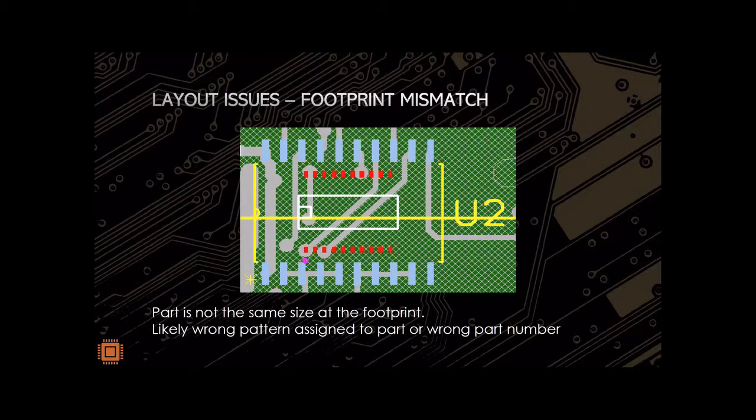If it's a critical IC that you must have on your board, then the only option is to redesign the Gerbers. But if it's in a family where you can choose a different package model, then you can actually give us the updated part number. We'll double check the footprint again and make sure that it fits before we go ahead and proceed.